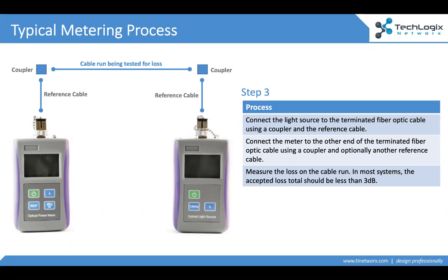When you do that, you're basically introducing contaminants into this brand new system that you've just installed. So these reference cables give you a way to really wear down those connectors and replace them for a couple of bucks, as opposed to the connectors that cost a little bit more that go onto these trunk cables. So any metering kit should come with couplers and reference cables. Use these guys. This is a pretty important part of the system, okay?